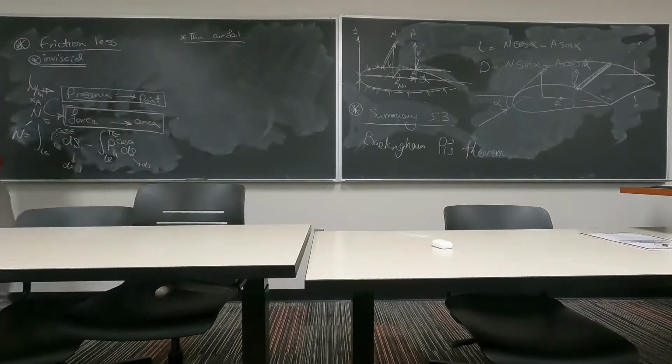So how can we simplify that with that assumption? How can we simplify this equation with the assumption of thin airfoils? What is going to change here? Theta is going to be close to 0, so cosine of theta is going to be close to 1. So we can take the cosine and theta out, right? And then you divide everything by q infinity.